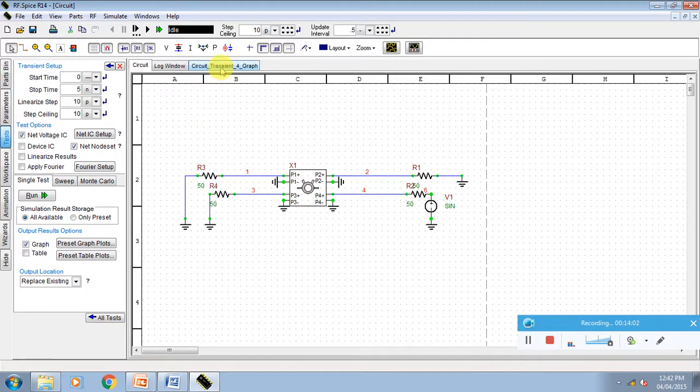If you excite at the P1 port, you are not getting the output at P1. But always you are getting the output at the P2 terminal and P3 terminal. And these terminals have equal amplitude, equal phase and half of the power division. So 3 dB power is divided between the P2 port and P3 port, and the P4 port is isolated. So this is basically called the rat race functionality, where you are getting the summing signal and a different signal over here.